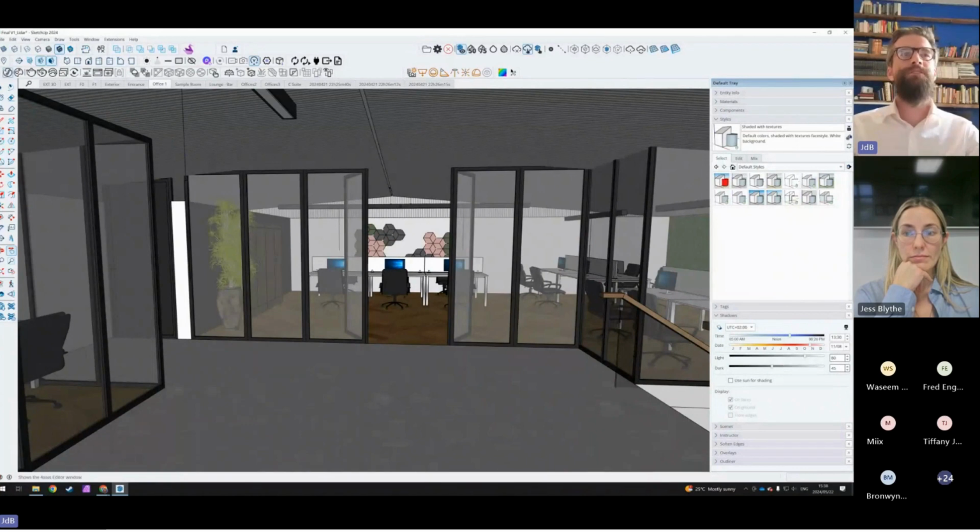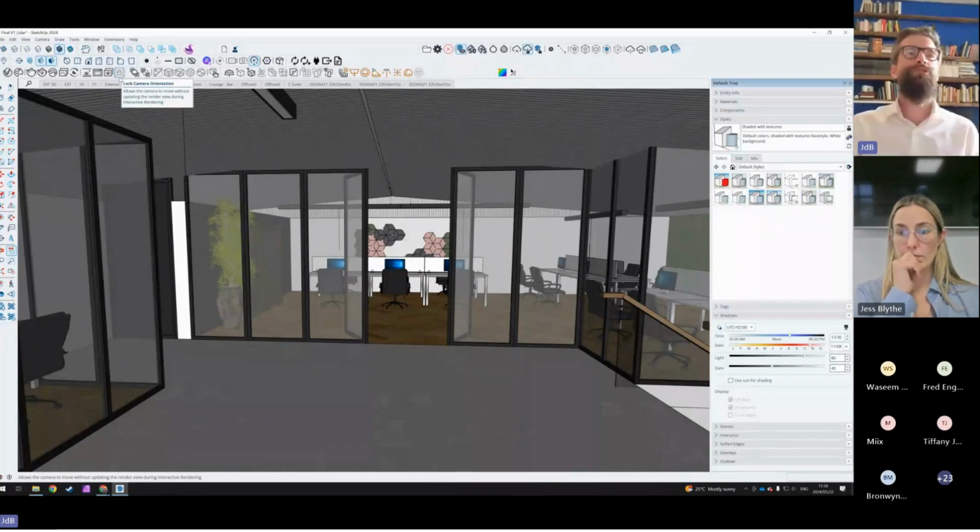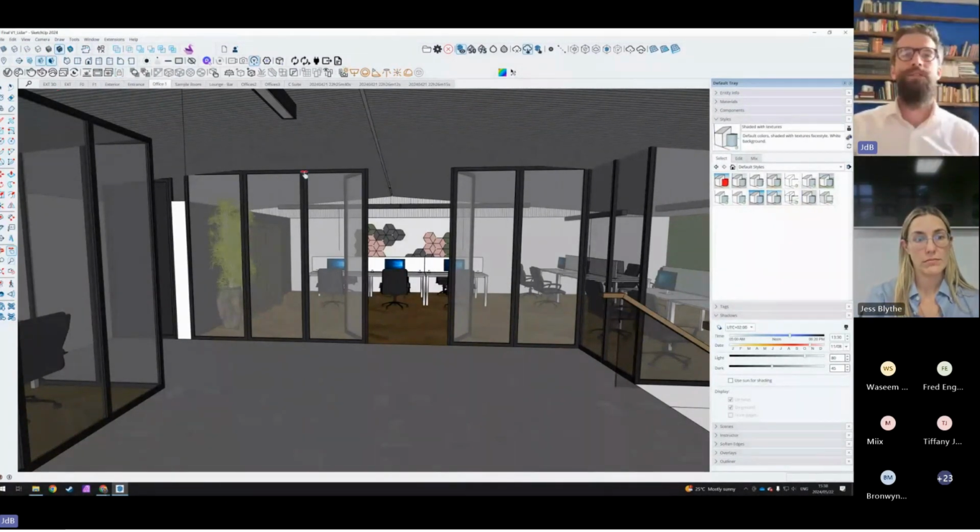So V-Ray comes as a very large tool set. You can see the 4 menu bars here at the bottom that you use to create these renders. And rather than the one-click solution of ambient occlusion or SketchUp diffusion, there are a lot of sub-menus and details that you can use to create a true photorealistic image.